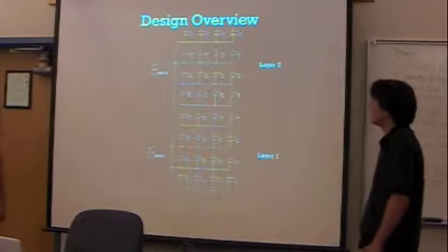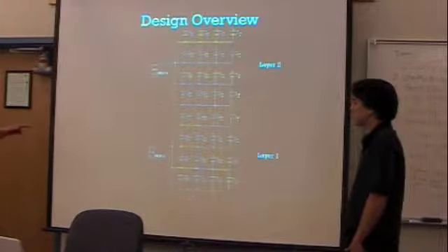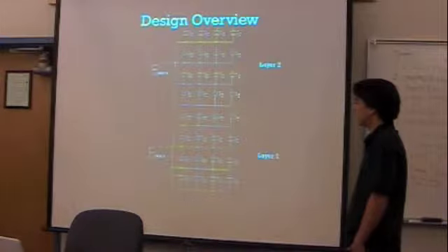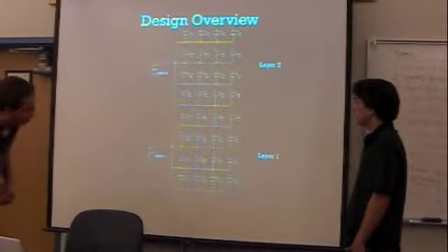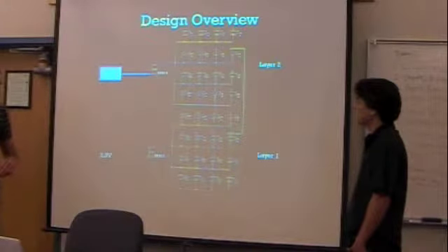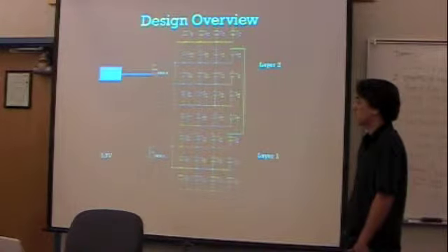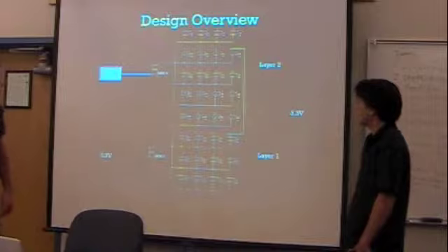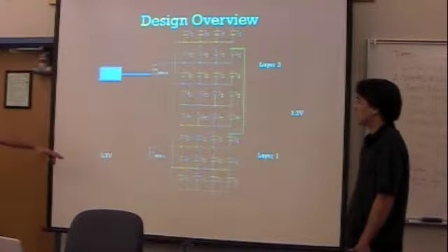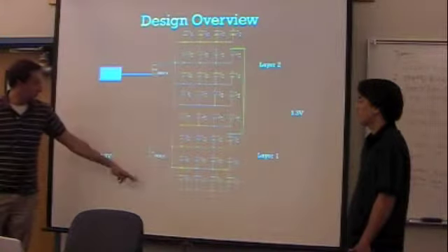As Nate talked about, the different layers within the cube are controlled by the NMOS, which connects all the cathodes within one layer. So the 16 cathodes are connected to one NMOS, and then all the anodes for a layer are connected to the corresponding LED above it. So there's columns connected together, so 16 columns and 4 layers. To operate it, you would provide a gate voltage higher than the source on the NMOS to activate the MOSFET, which would allow current to drain down to ground.